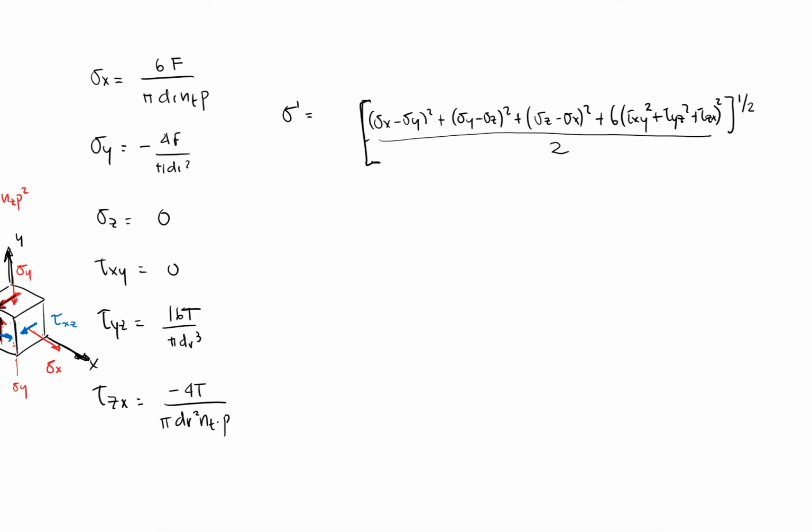Basically, you would be able to measure the major diameter. I'm just going to write it with words. You can have information about your major diameter because you can literally measure that: 32 millimeters.